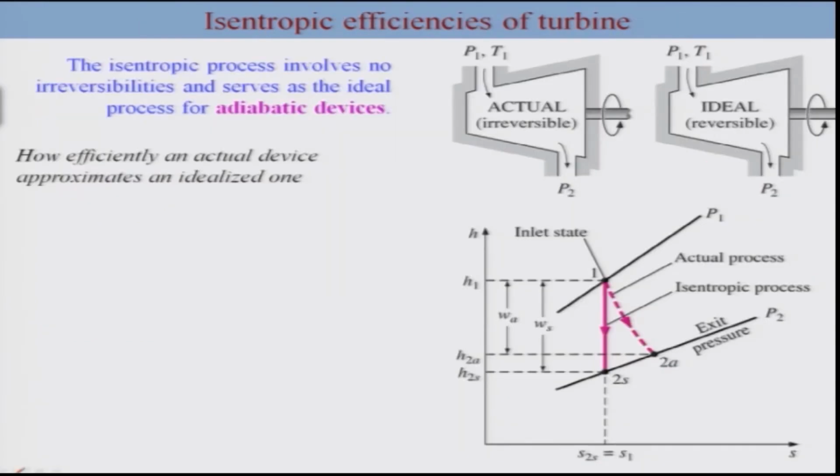So we have already discussed the kind of work for the reversible case. The turbine, we looked at the compressor. We looked at the necessity of intercooling in order to reduce the work required for compressing gas, for example. Now if you want to compare the efficiency of such a device, we look at kind of idealized model. Okay, and this is something which we have already looked into when we discussed the cycles, where we have considered the Carnot cycle, the idealized fictitious kind of cycle, as a theoretical limit.